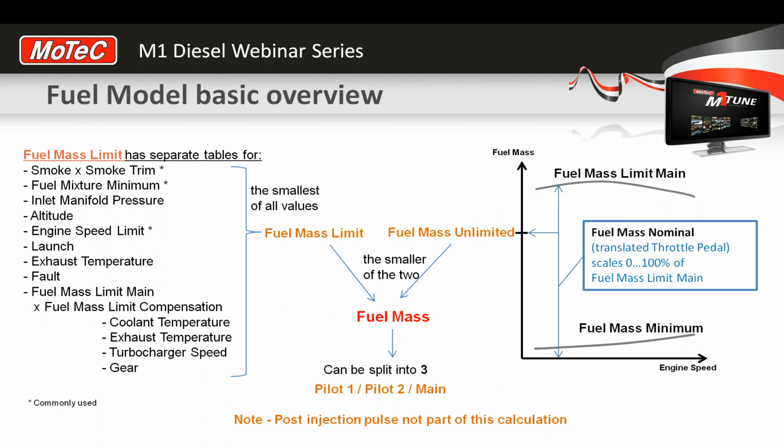It uses lambda estimate. Your whole purpose in life, well, not quite, but it certainly makes your life a lot easier if you can get those injector and air mass flow calculations, or calibrations, correct. Then you can just enter the lambda you want to run and it'll flatline it for you. It really works well. Either or both in combination are the two tables you'll actually do your fuel tuning with.